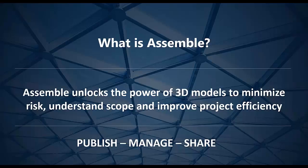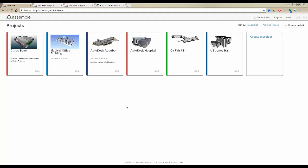The workflow of using Assemble is very simple. You just publish your project to your cloud-based site. You can manage the project in cloud, and then you can share it with all of the stakeholders of the project. Assemble doesn't have a really big software to install. There is just a plugin that will be installed on top of Revit and AutoCAD, and you can publish your models from Revit or AutoCAD into your cloud-based site.